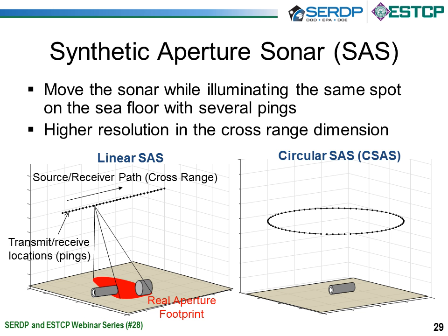So the underlying technology that we're exploiting is something called synthetic aperture sonar. This is a coherent signal processing technique in which we take a sonar and we move it along some predefined trajectory, and we emit pings, and we record the amplitude and phase of the backscattered signals as we move along the trajectory. The raw data that we get out doesn't look like an image, but we can beamform the image in post-processing to create a variety of different data products that are highly information rich because we have acoustic information related to both the image of the object, and we're looking at it from many different angles because the beam width of SAS systems tends to be very large.